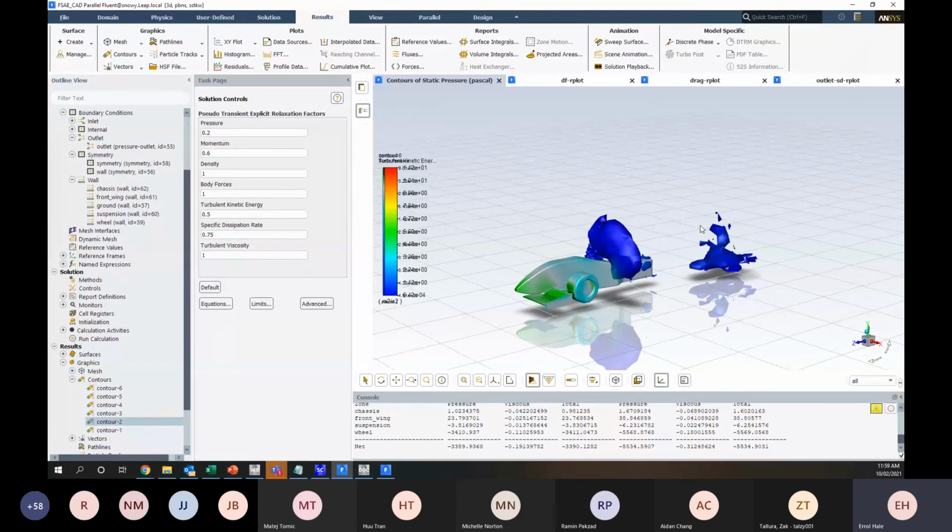All right, so we can see we've got big problems here and here in terms of our residuals. And we could assess that as being maybe a mesh problem or maybe it's a transience thing. Maybe that's where the wake is the most chaotic. And it may be that we want to reduce our mesh size in those areas.